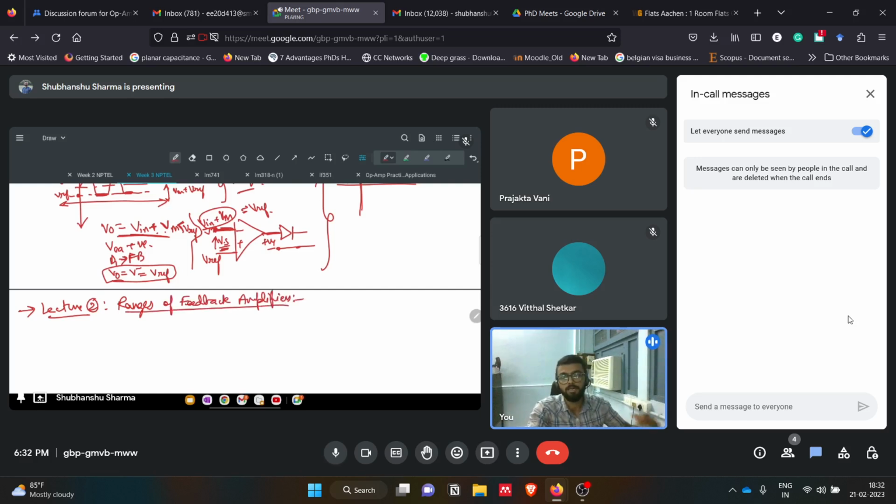we cannot simply get the gain that we want. It depends on some value. And what is that value? First of all, there are two values which decide that. First is the plus minus V supply voltage, which we are giving to the op amp. Since this op amp is run by these two supplies, we cannot get a gain beyond this. Otherwise, it will be a violation of the law of conservation of energy. Okay, if you are giving 5 volts, how can you get 6 volts? Got it?